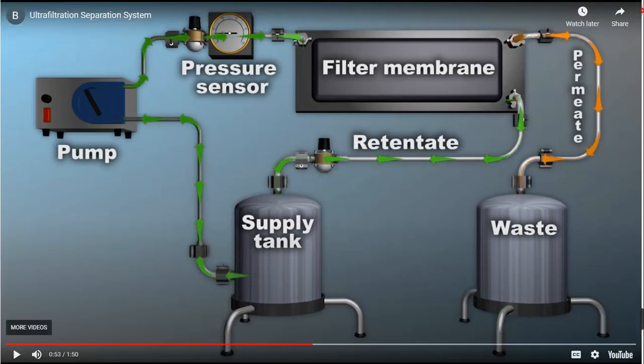You can feed the retentate into the supply tank so that it is continuously supplied; this is online, continuous mode, to permanently remove all the components other than the GFP. You can see here that all the waste materials are collected, and to a particular extent you will get only your retentate, and this outlet is going to decrease. At that point you can stop the ultrafiltration. If there is no permeate, no protein at the outlet, you can check the sample, and if there is no delta A, that is absorption at 280 nanometer, you have to stop the process, move all the retentate into the supply tank, and collect it.